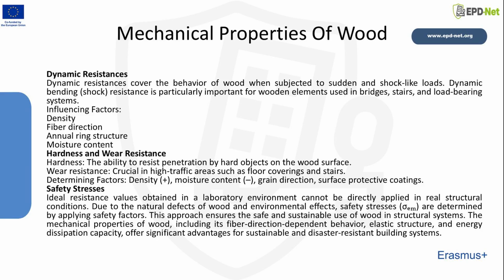Dynamic resistance covers the behavior of wood when it is subjected to sudden and shock-like loads. Dynamic bending resistance is particularly important for wooden elements used in bridges, stairs, floors, and load-bearing systems. Several factors influence dynamic performance, including density, fiber direction, annual ring structure, moisture content, knots, and defects.